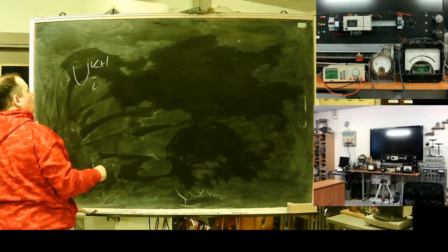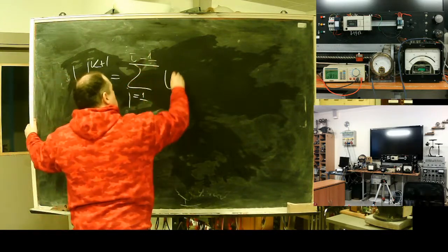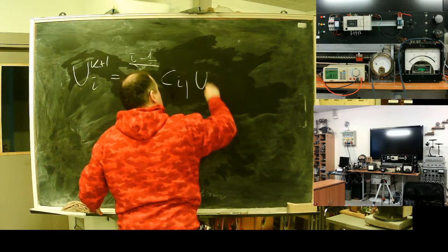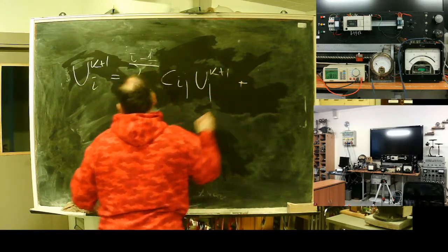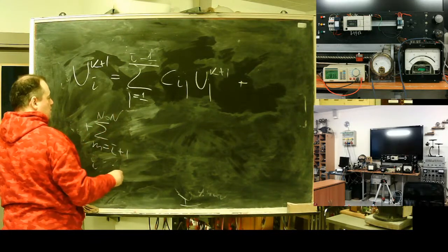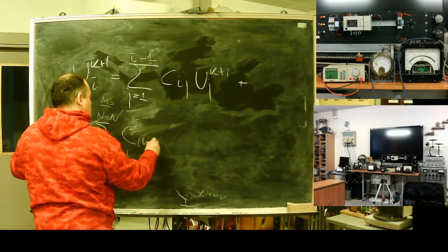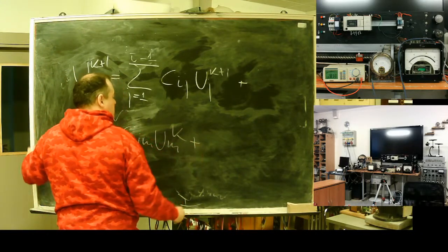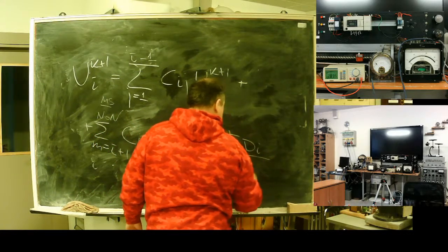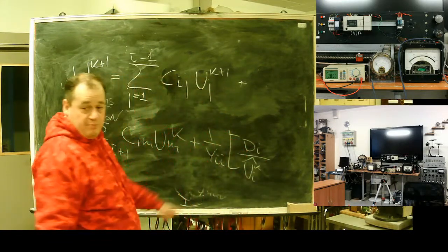The next voltage in node number i I can define as a sum from 1 to i minus 1 of the next, plus a sum from i plus 1 to the number of nodes of the previous, plus 1 again, divided by the voltage from the previous step, but conjugated.